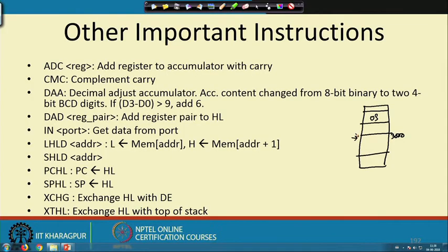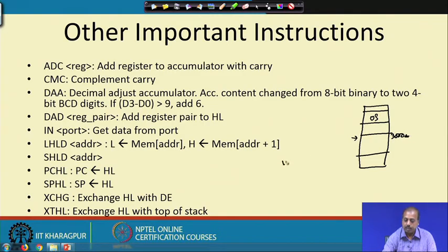There is no direct instruction to load the PC register. So, what the operating system does is that once it knows the start address, it loads the value 3000 into the HL pair and then executes the PCHL instruction. So, the PC now gets the value of this HL pair. Once the PC has got the value 3000, it automatically starts executing from this point.